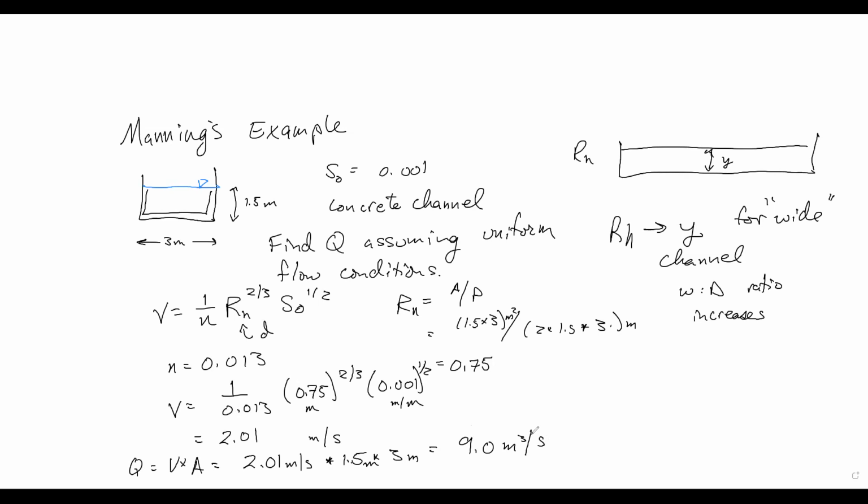Okay, not a hard problem, but the thing about this is we've got to make a lot of assumptions. In this canal, is this a perfectly sloped canal that's perfectly prismatic for a really long time? If we want to assume normal conditions, we can say that we're at a normal depth. So I'm going to introduce that. It's going to be the last thing we introduce, a normal depth, or y_n. And this is the depth at uniform flow.